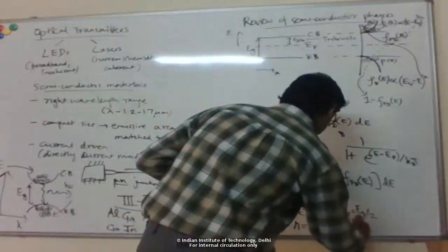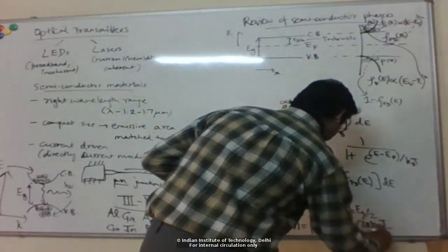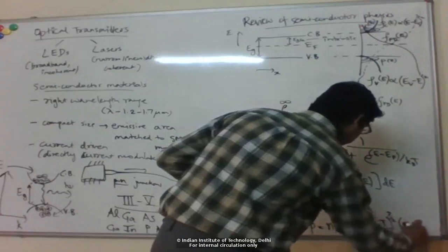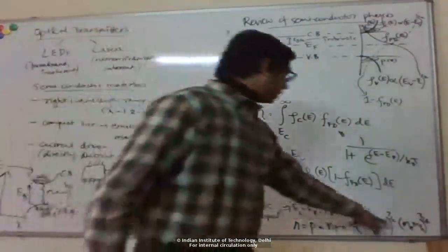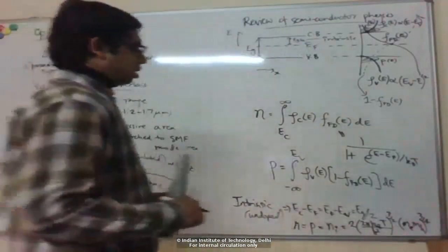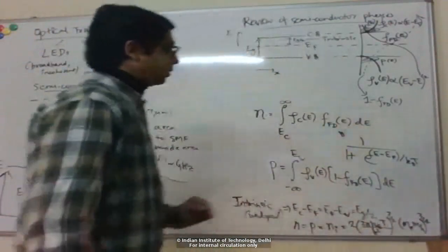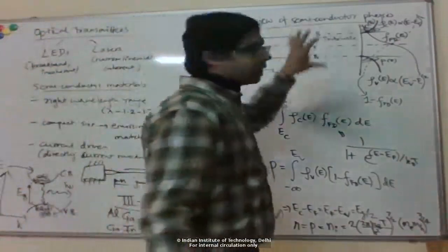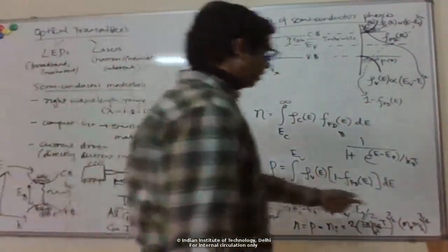which basically depends on the temperature and some material properties, like the effective mass of the electron and hole. So it depends on temperature here; typically it scales with T to the 3/2, and other constants: the Boltzmann constant, the Planck constant, and here we have the effective mass of the electron and effective mass of the hole. You know that the inertia that the electron or hole feels in a semiconductor is different from the bare mass of the electron. So here we have the effective mass.